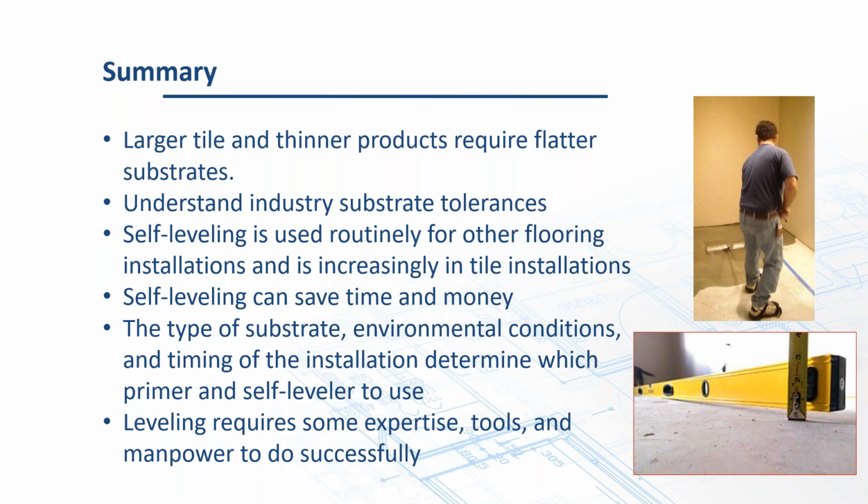So again, make sure you understand what you're trying to achieve, where you need the leveler, where you don't. If you're just trying to cap an area, that's not so bad. Gauge rake it and get out of there. But if you want to make sure that it's perfectly level, that's a different animal. Now you've got to have a really good feel of the topography of that concrete substrate you're going to pour into. Man these projects properly. That's really important, especially when you're trying to keep wet edge to wet edge.